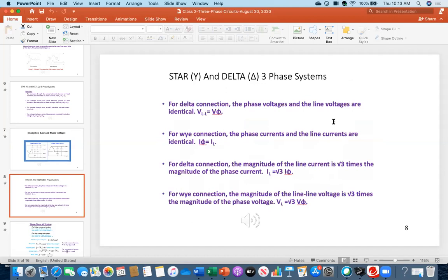For current measurement it is okay because it is connected in series with one coil, but to measure voltage, you need two points. So this is actually line to line voltage, but frequently in literature, in books, anywhere, they simply write just line voltage. But keep in mind, this is line to line voltage. That is VLL, VL dash L, meaning between two lines, equal to V phase. This is the phase symbol.